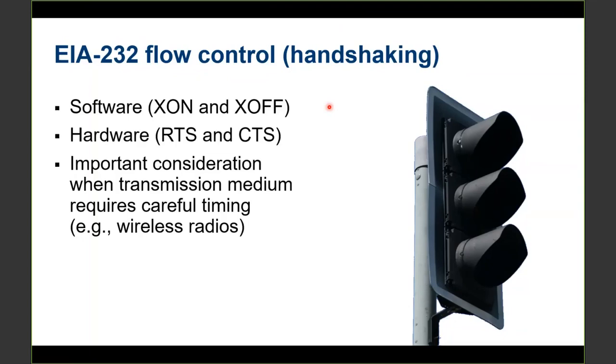And that usually comes into play whenever the sender and receiver can't always process the data at the same rate, and so it can use those pins as a mechanism to control the data flow. Now, software flow control is used by SEL extensively in our SEL protocol, and it's used widely in other places too. But instead of using these two pins to control the flow of data, you're actually sending characters.